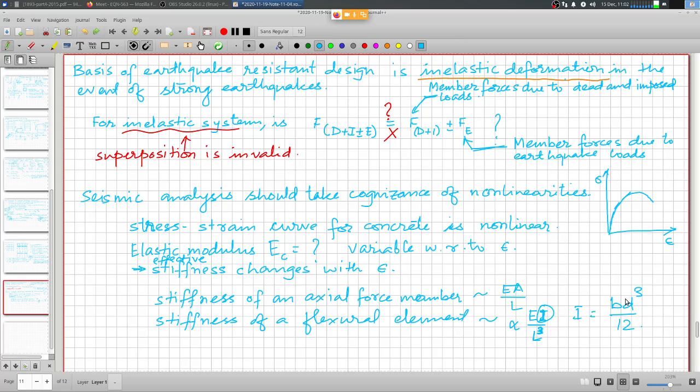So practically you do not see any beam, and that obviously has a very reduced stiffness, because the depth is very low. You may increase whatever width you may have. Of course, there are limitations to having the width of the flange as an L beam or T beam, as the situation may be, but the stiffness is not really much if the depth is very low.